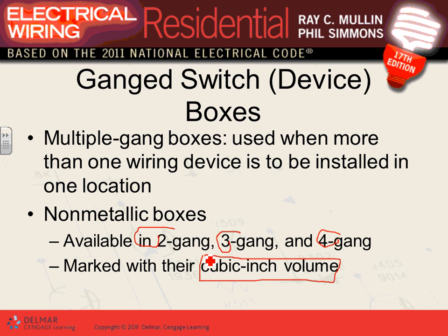The metallic boxes, you can gang them. Did you guys, the ones who did electrical work, gang them, put them together, right? Gang a bunch of them, so you can gang as many as you want, up to 8, 10 sometimes, depending on the brackets that you have. Why do we gang them? Here you go. Here's a very good example of ganging. There's 1, 2, 3, 4, 5 receptacles. If I would use gangable boxes, I need 5 single device boxes ganged together to create room for 5 switches. That's what you're ganging as.